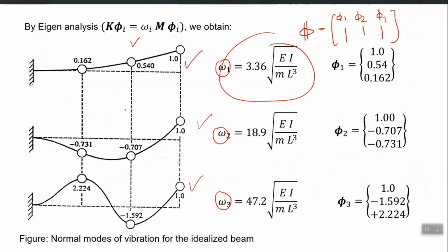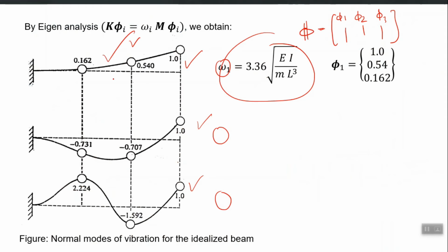Let me go back and show you, this is the first mode shape. So I deform the building similar to first mode shape, and the resulting free vibration is telling you that the first mode will have the highest contribution. If I deform it in the second mode shape and then let it vibrate freely, it will have the highest contribution from second mode shape. In case of ground shakings, most of the times the first mode shape is excited the most, right? So the effective earthquake forces do not give initial conditions which resemble second mode shape or third mode shape, right?